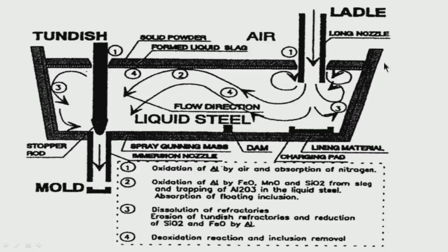Now, this is the total Tundish. From the ladle, liquid steel is coming here. We do not want liquid steel to go straight away to the exit of the Tundish. Why? We want liquid steel to remain for some time in the Tundish. What we call the residence time. Residence time of liquid steel in the Tundish should be high, so that whatever inclusions or exogenous entrapments try to ingress into liquid steel will get adequate time to float up.